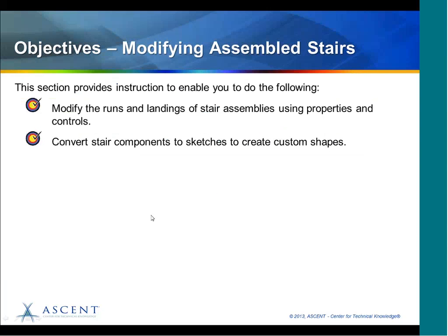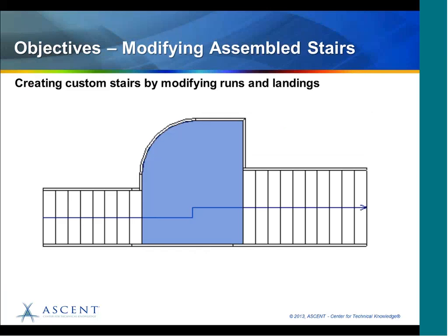Well, let's go ahead and talk about modifying the stairs, because creating a stair is fairly simple, but where the really important part comes is when you start modifying. So we're going to talk about modifying the runs and landings, using properties and controls, and also converting things to sketches so you can create more custom shapes.